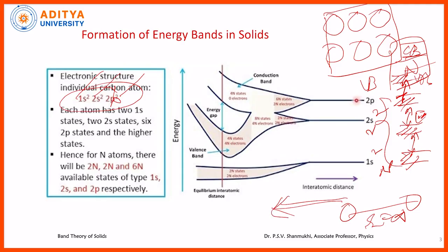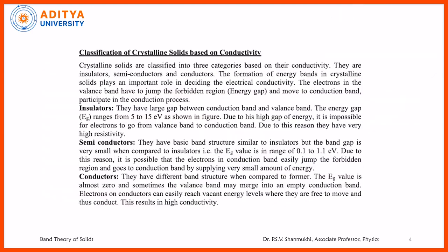In the case of one isolated atom, the individual electrons are arranged among various energy levels like 1s2, 2s2, 2p6 as per the electronic configuration. Whereas in a solid, as the interatomic distance is reduced very much, electrons having the same range form energy bands, so several energy bands are formed. Lower energy bands are insignificant. Among the upper energy bands, only three are significant: the valence band, the conduction band and the forbidden band. In this way, the energy bands are formed.